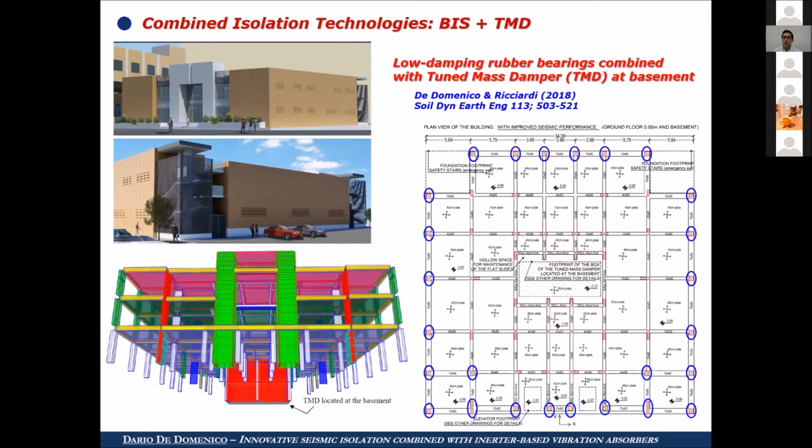mass damper. We applied this technology for the earthquake protection of a university center located in Palermo in South Italy. In particular, we developed a project by planning a traditional set of rubber bearings placed around the perimeter of this building in order to increase the torsional resistance of the building.